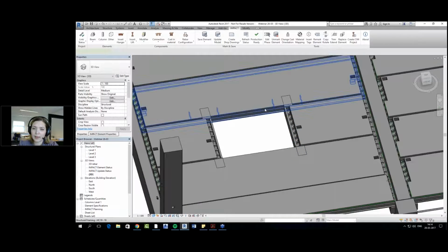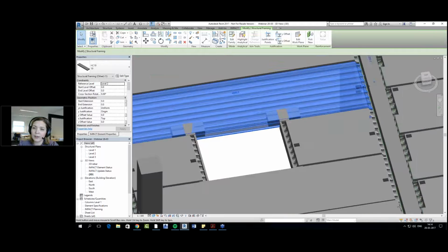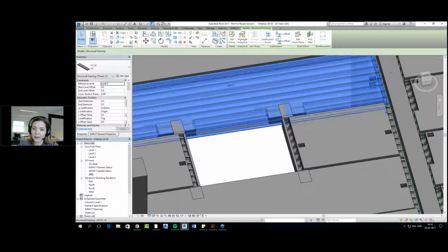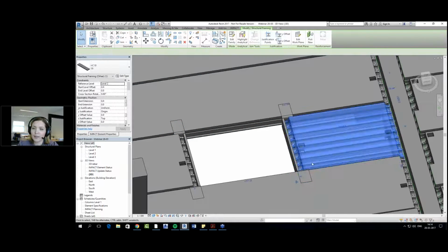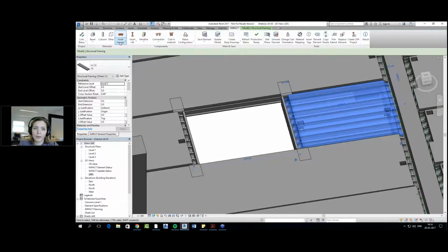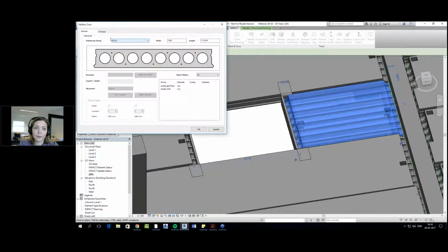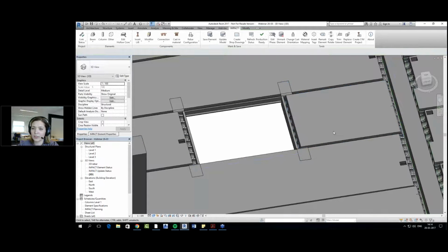And if I click on this element, you can see that as we have predefined, we have core filling where we have hangar detail. So the width is 600 millimeters, and we have 2 cores filled. Of course, now I have to change the end cap for those 2 hollow cores because they are new hollow cores. I have to adjust. So if I say edit hollow core, I can just go for the end caps and say test, test, and this is changed.